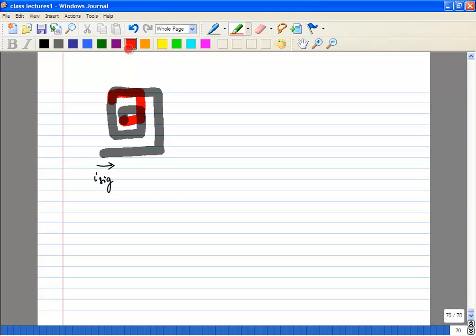So you may do something like this, and you might be able to use multiple metal layers. And what that means is, if the current flows through like this, it will start flowing through like this. So you try to maximize your overlap area. Okay, so this is the last kind of case we'll look at.